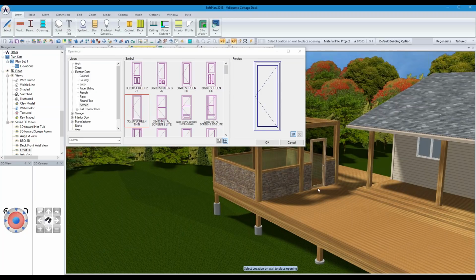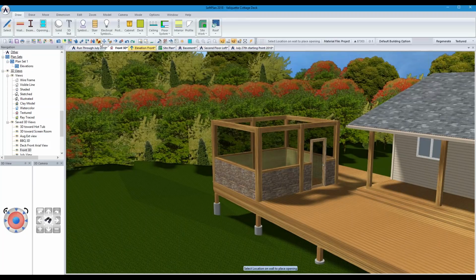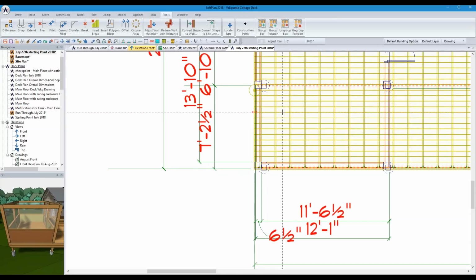So now if that screen door isn't exactly the same finish as the others, something you're going to see me use a lot is the surface copy paste. You click on a surface that you'll want the other item to match, and then you click on that item and it'll actually apply it. So it's applied it to part of the door, and you just click on the additional pieces of the door at that point.